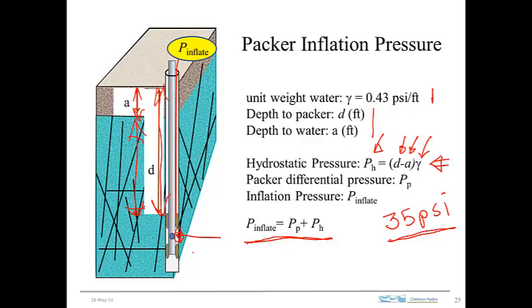So we do a slug test, and these are pretty modest slug tests. The total displacement of the slug is maybe, well, let's say it's 2.4 feet. That would be equivalent to 1 psi. So we have 1 psi of pressure difference here between the packers, and we have 35 psi of pressure inflating the packers. So these packers should remain sealed against the borehole wall in this case. But if we were doing other tests that required higher pressures, then we would need to go to a higher pressure packer.